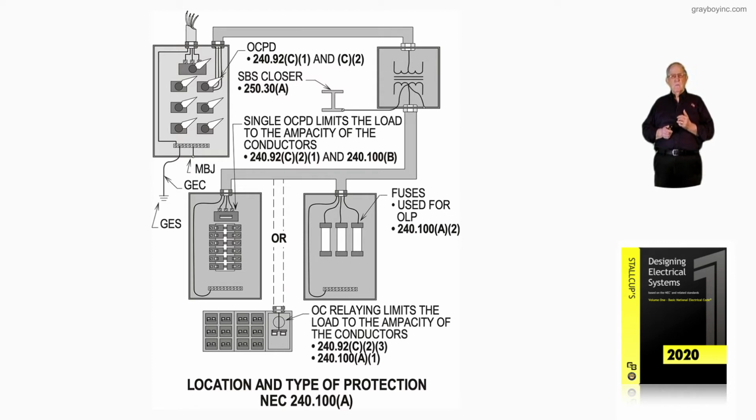But now the equipment that you see in the center is a relaying type system. And I could actually design that, as the installer, to have a relay at the service equipment that communicates or compares, as we'll see later, with the downstream relay. If it loses more current, then we're going to open it up. If a ground fault, short circuit, or say an overload occurs that we know would damage components, conductors, terminations, and so forth, then we could open it up.